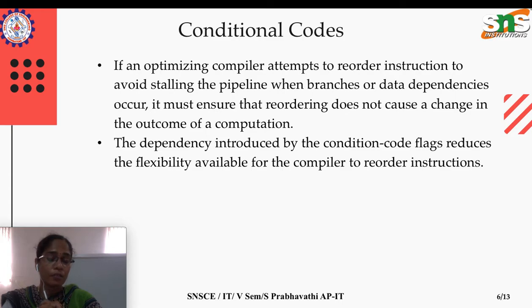Then we looked at addressing modes in the instruction set and how they influence the execution of the pipeline. The other topic is conditional codes. Conditional codes means when we do some calculation, say, for simplicity, addition. After addition, when the result of the addition is negative, the processor will store the outcome of this addition operation in a separate special register.